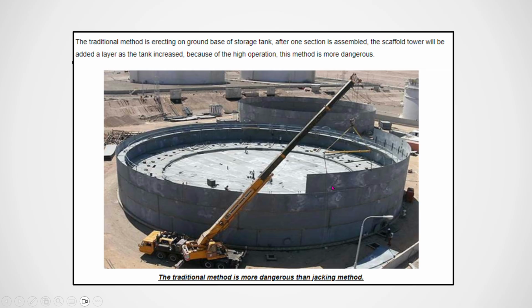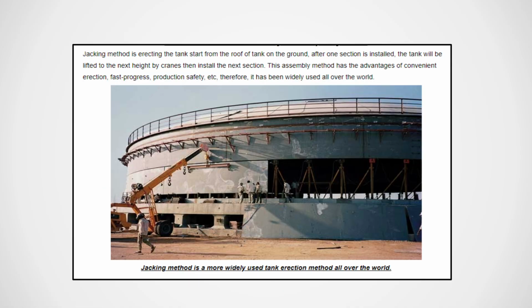For a small tank it is okay, but if your tank height and diameter are more, then holding the plate with the help of the crane will make it very difficult to match the gap. Every time you have to change the scaffolding, and the scaffolding also has to be made very strong, otherwise a lot of accidents will take place. Though this is a traditional method, we are not following it. We are following this other method.